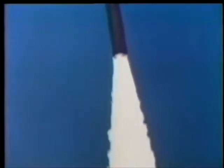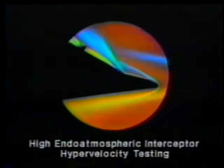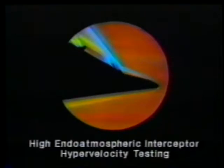Initial validation tests will be conducted using a standard Minuteman I ICBM with a KKV mounted as the payload. In its operational phase, the GBI will be smaller than the second stage of a Minuteman. The ERIS kinetic kill vehicle carries all its own systems, including avionics, divert propulsion, infrared seeker, and kill enhancement device to improve lethality. The first full ERIS test flights are scheduled for 1991.